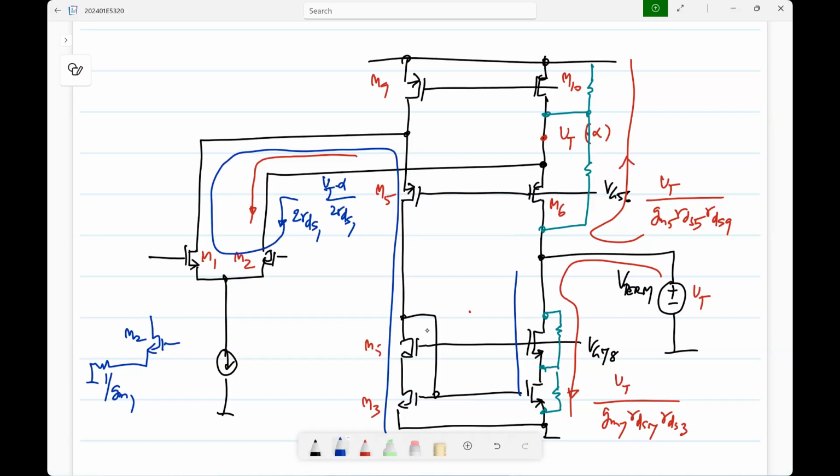But the net result is the conductance due to, so all the conductances are in parallel, right? It doesn't matter how you add them up. If you look at the current component, half of it goes up and the other half goes down. This is just like in the regular simple differential pair, it's the same thing. Although you get gdsp plus gdsn, the part that goes up is gdsp plus gdsn by 2. The part that goes down is gdsn by 2. The same thing happens here. Is that okay? Anything else?